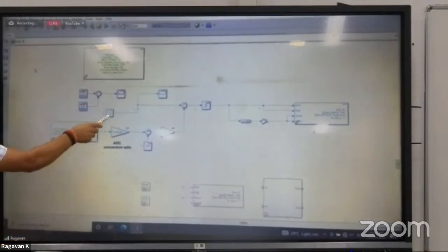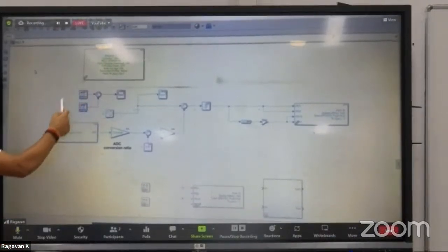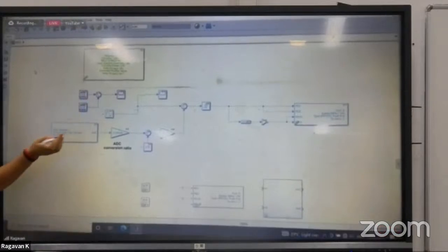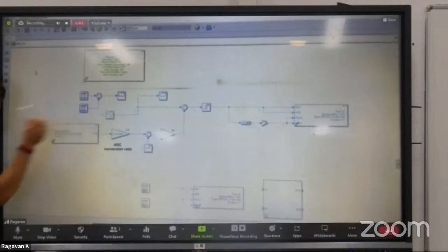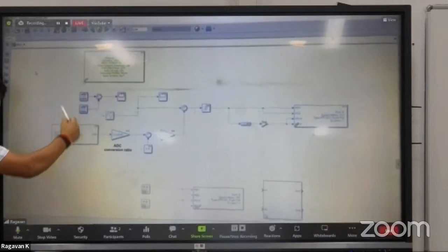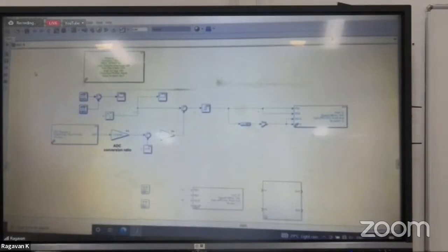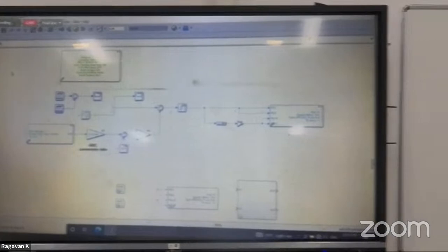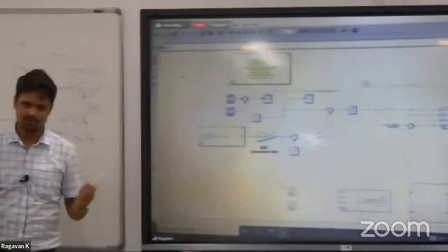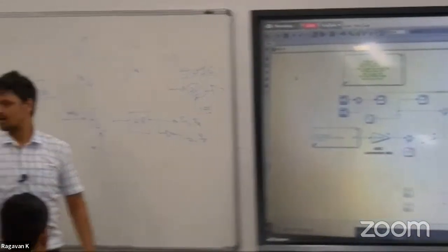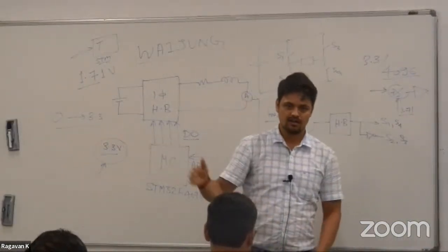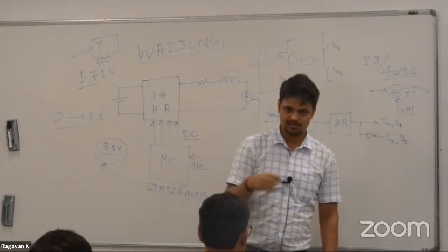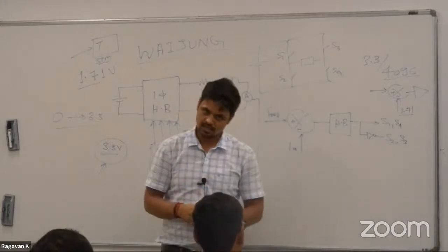So this is for sine, and this is for quasi square wave, right? So first we will run with sine, we will see how it is working, and then we will see with that. Performance cannot be, I mean, up to the expectations like simulation. You can have a wonderful waveform, but here we are having a limitation with the inductor, because the inductor is iron core. Ideally we need a ferrite core which can sustain the frequency switchings, right?